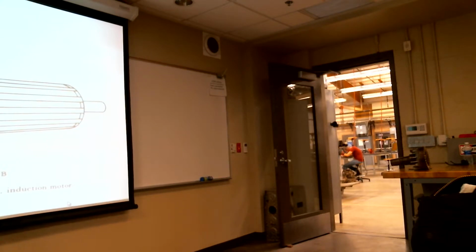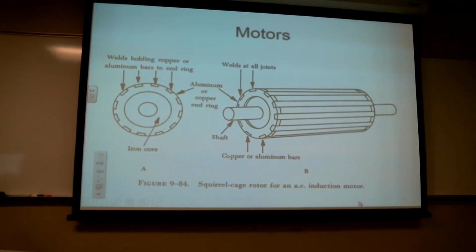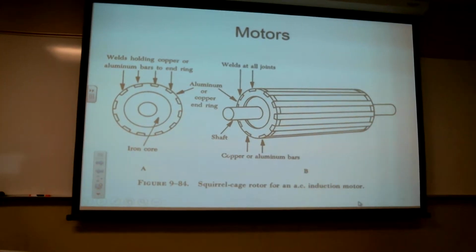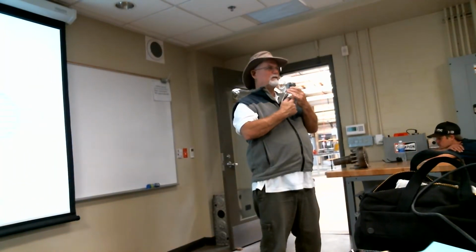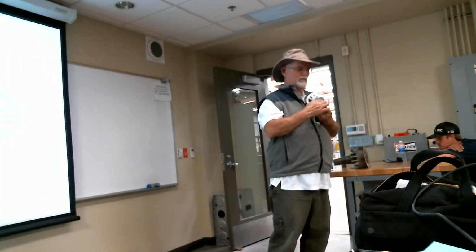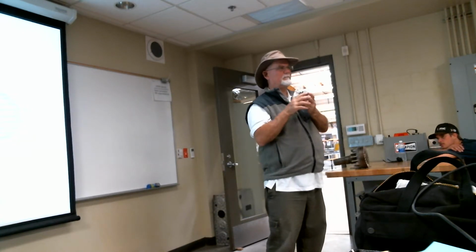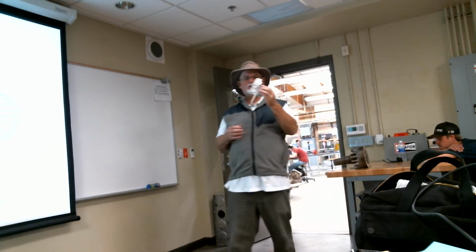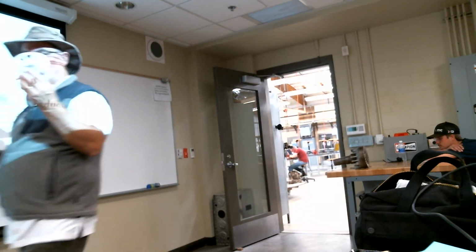Let's go to the other end of this text. Little bitty lightweight motor. You can't really see it in here, but if I took that out, you'd see a bunch of little bitty bars in there. In this particular case, instead of having 3 phases, we're only going to have a single phase going to this thing. So what's going to happen is it's going to build up the magnetic field, and then flip around, build up the magnetic field, and then flip around and build up the magnetic field. So this thing isn't really going to know which way to start unless we play with it some.